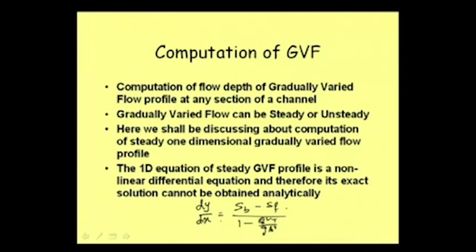This differential equation is non-linear, because on the right hand side we are not getting dy/dx as a function of x only. This is rather a function of y, because SF, that is the friction slope, or the top width, or the area, all these are basically functions of y.